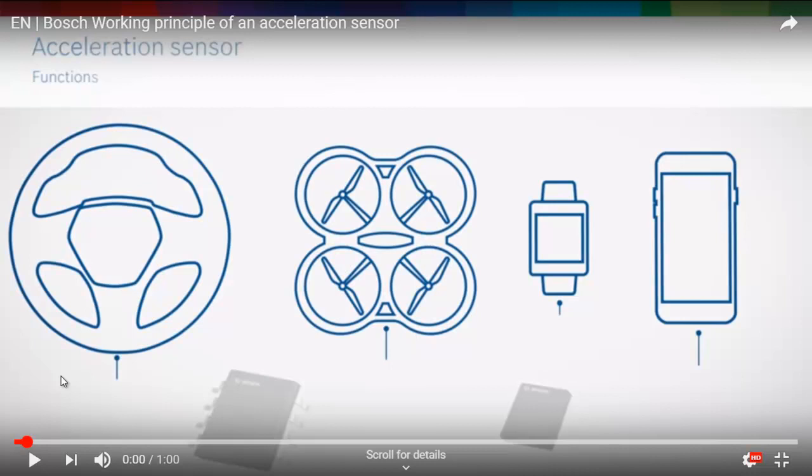In high-end phones, you can use two accelerometers, one very low power in order to have a longer battery duration for most applications. But when you need a very precise measurement of the acceleration, just for those few minutes, you turn on the high consumption accelerometer.